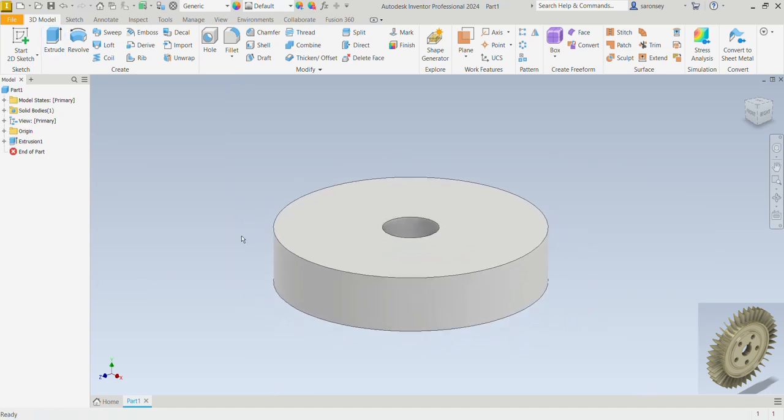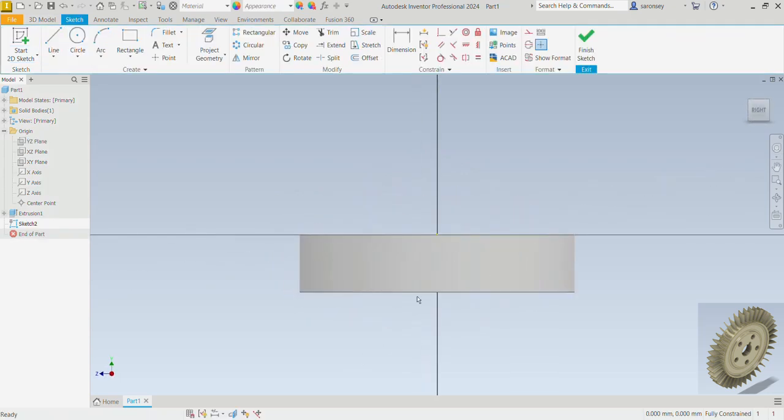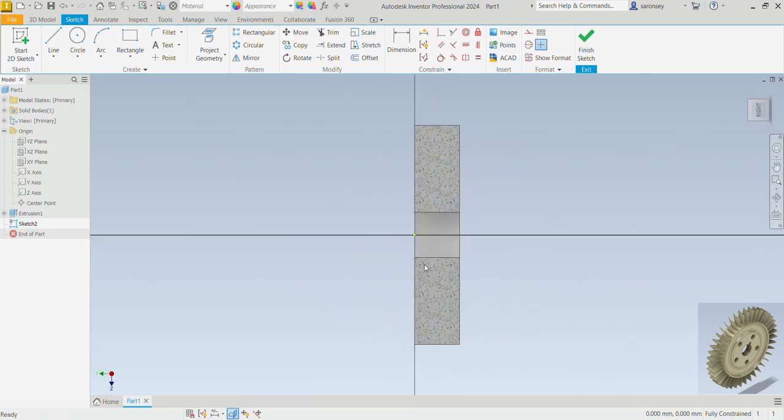Now let's get the 2D sketch command again and create this sketch on, let's look for a plane to work on, which is going to be the YZ plane. Now I want to slice this so I see that plane. So come down here and choose the slice graphics option. Let me also turn this around.